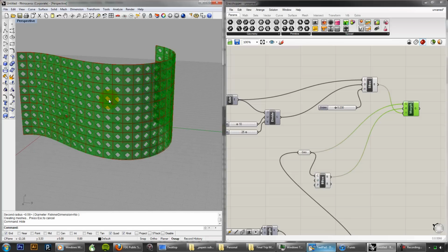I want to caution you, this works really well, but A, it's very slow on your computer. It does not update very fast, so you have to be very careful about what you plug into it. B, it is not the best way to solve a lot of your problems with your projects. The best way to make a geometry parametric across any surface is to construct it using points and lines and planes and different kinds of topological stuff that we've talked about.